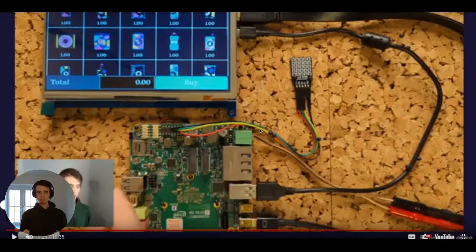The communication between the applications is done through WebSockets. The API used, which you will find documented as part of our Oniro documentation, is inspired by WebThings. So the UI application is driving an HDMI display and the control application is driving a 5x5 LED matrix, which simulates different operations on the vending machine.